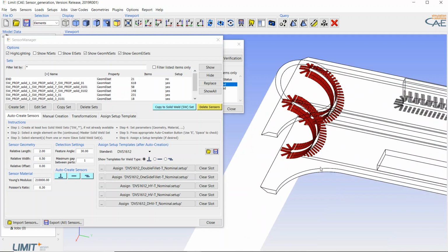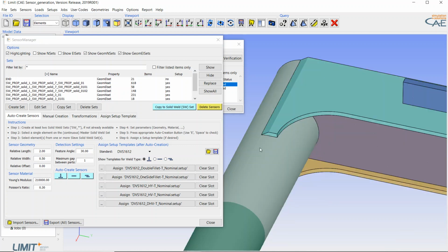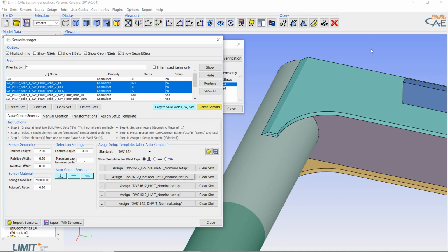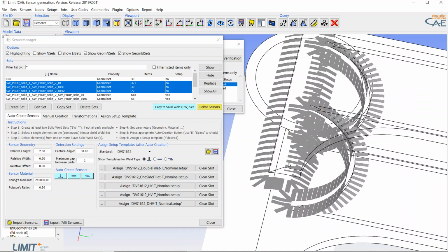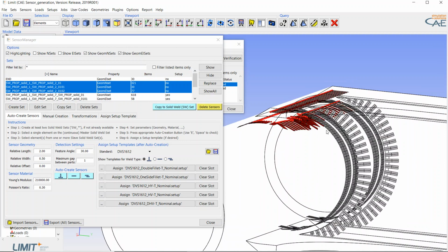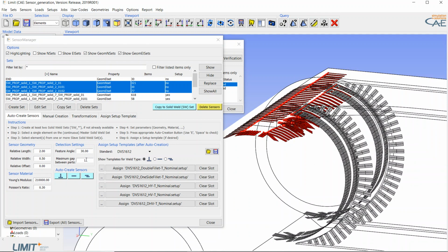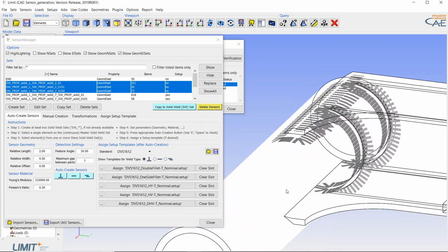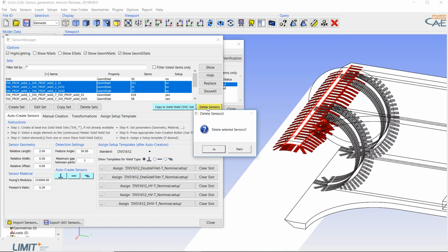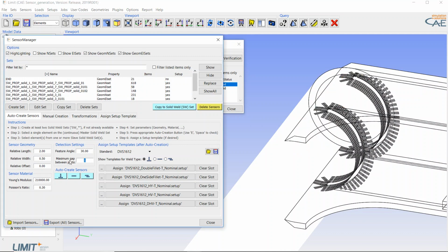Okay, so if I, for example, use these settings for the overlap situation between the tube and the upper flange, this here and this here, again continuous sheet at first and then the attached sheet, and overlap. What does this look like? Doesn't look very good. The sensors in the continuous sheet are not positioned in a straight fashion, which means that this maximum gap parameter is not adequate for this type of geometric situation.